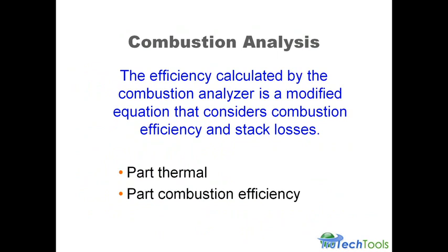We're not. We're actually doing the testing at the stack. So we don't know how hot that flame got. We don't know how much heat that flame produces. But what we do know is how much we lost, we're losing up that stack. And so that's what we're doing. It's a modified equation that is very representative of the efficiency of the appliance that we're testing.